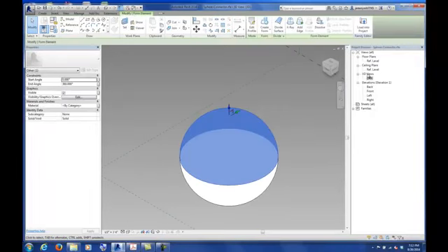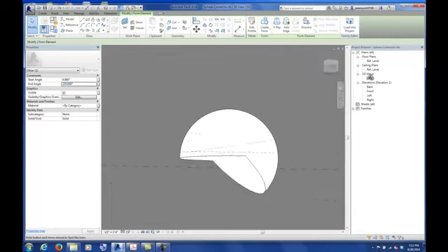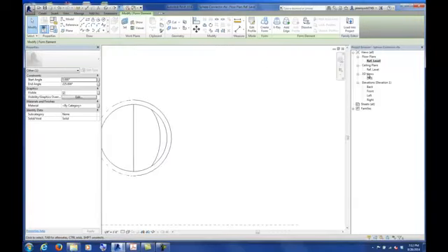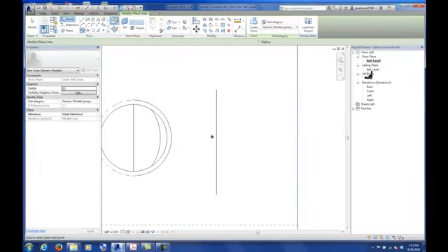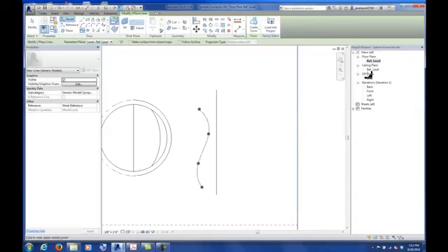Now what I like about the hard way, which I just showed you there, is that when you select that sphere once it's made, it has a start angle and an end angle, and automatically it goes to 360. But I could type in 225 for my end angle, and it'll kind of start to cut away and not do a complete revolve. So you can kind of get these other shapes out of that if you want. One thing that I want to show again with that, instead of doing a sphere, if I were to draw another vertical line, and let's say I do a squiggly line with that spline tool.